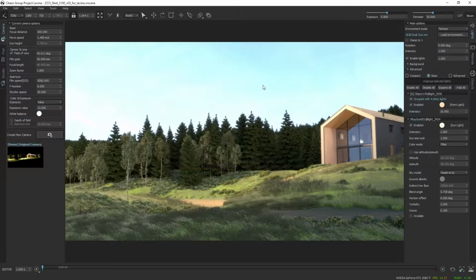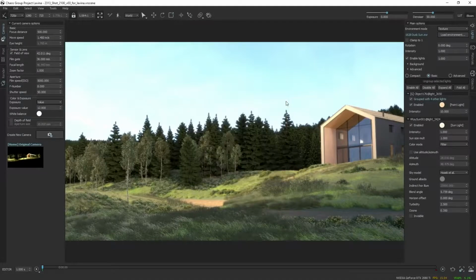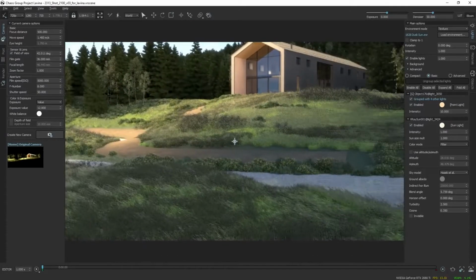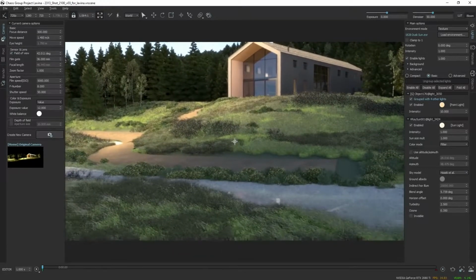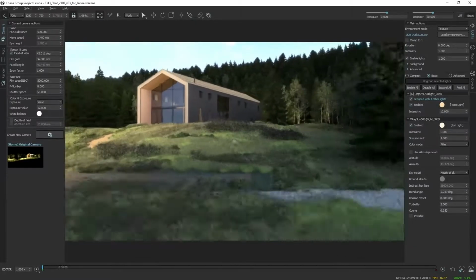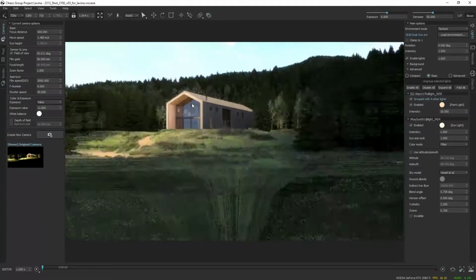Here is also the mouse sensitivity, which is an important parameter you might want to tweak if you want to speed up or slow down your mouse, for when you want to find the perfect fine-tune. So now it's 3ds Max style, which is just middle mouse button panning, Alt and middle mouse button to orbit, and then Control, Alt and middle mouse button to zoom, or the scroller to zoom, just like in 3ds Max.